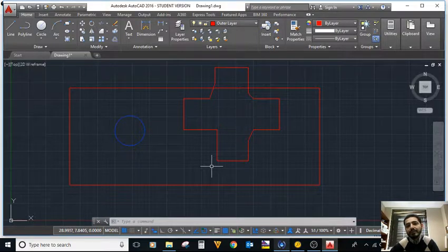If it's one piece, you can't do this. If you click on it, it's going to be one piece. So what you need to do is to explode it. That means you would bring this object into its original elements. It's going to break it into little lines here and there, so you can select a certain line that you're not interested to have anymore and delete it easily while keeping the rest of the drawing without any harm.